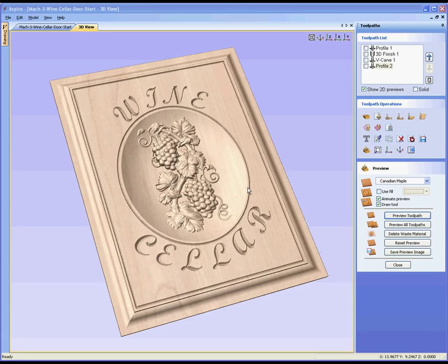The last thing, just to mention, was the fact that in that dished area we didn't do a roughing toolpath. In this case, we decided that our tooling would be able to cope with that because the initial cut is very, very light around the edge. After that, it's only stepping over 10% of the tool diameter, and so as it works its way through, the loading on the tool is fairly light.